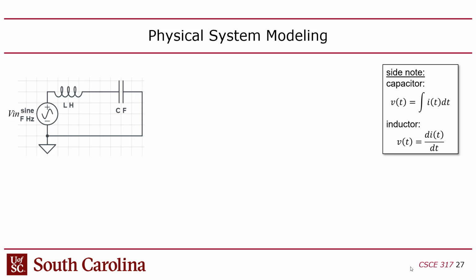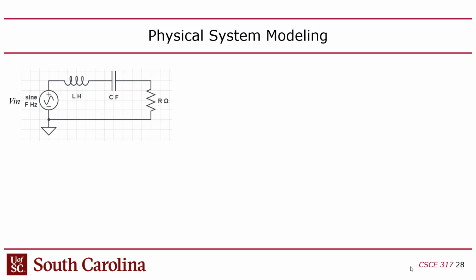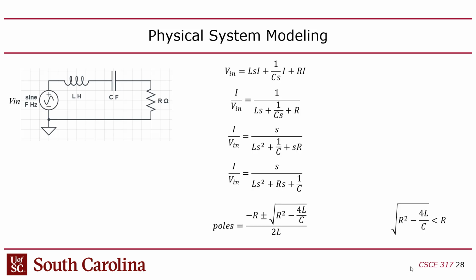Okay, and then finally, this turns out to be equivalent to RLC circuits. You can do the same thing. I'll just run through this really quick. You can calculate the S-domain transfer function here and find the poles. And as it turns out, if you build an LC circuit without any resistance, it's also unstable, right? But of course, in reality, you always have a resistor in there. And so you end up getting poles that are in the left-hand plane.